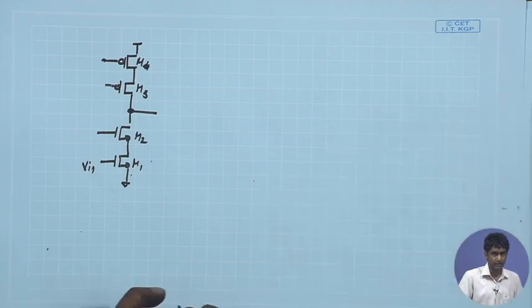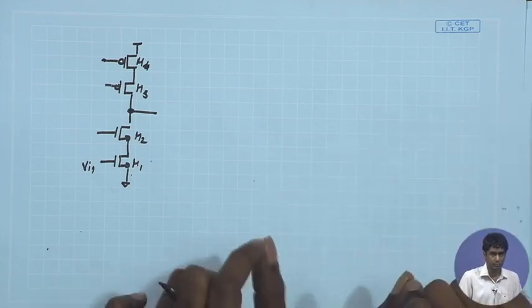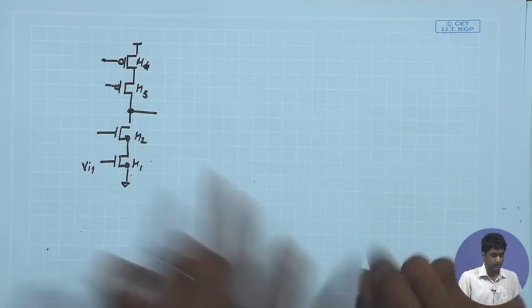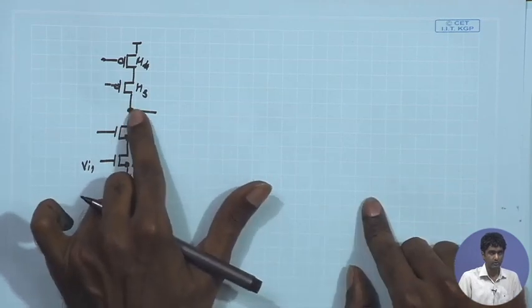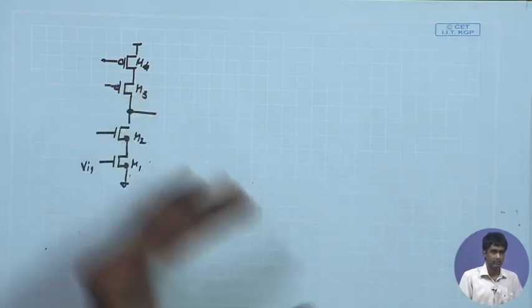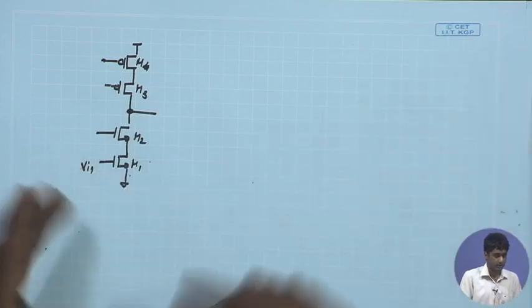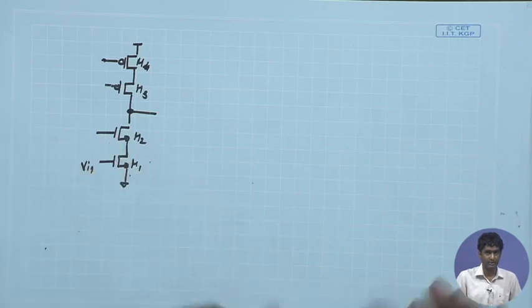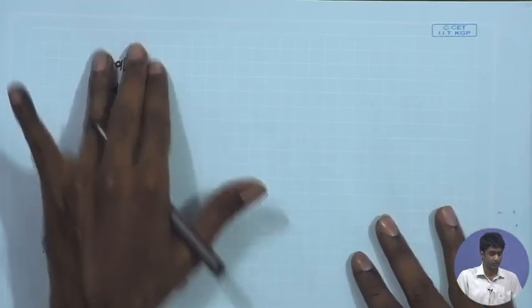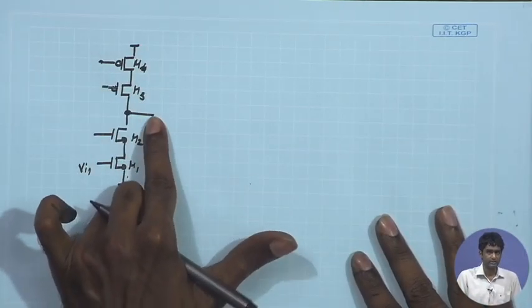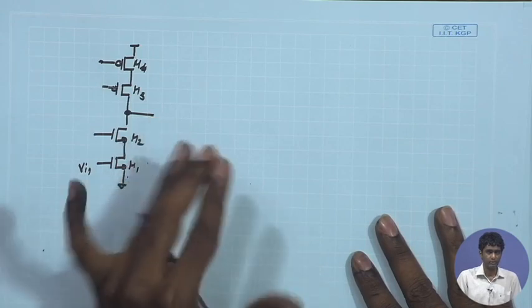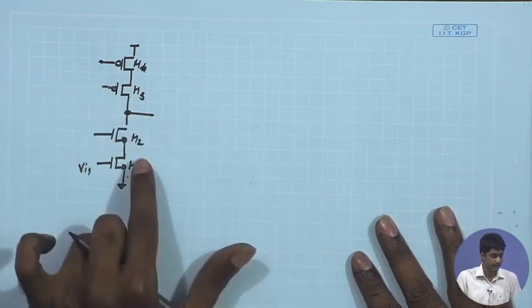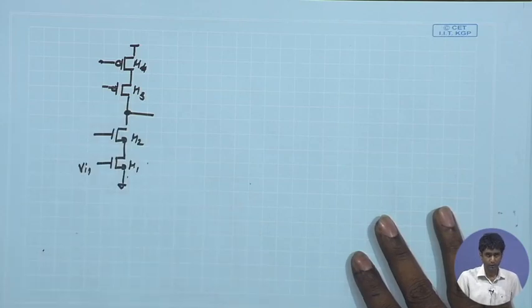So as compared to the two-stage amplifier where the two poles P1, P2 are comparable, here we have a dominant pole. One of them is already dominant and it is having a value GM_RO times lower as compared to the other one if I just depend upon the parasitic capacitances. And therefore, if I have to compensate the closed loop operation involving such amplifiers, I would like to just compensate this dominant pole. I would like to just push it towards further lower frequency and obtain an overall phase margin of 45 degree. So that is one of the advantage of this stage.